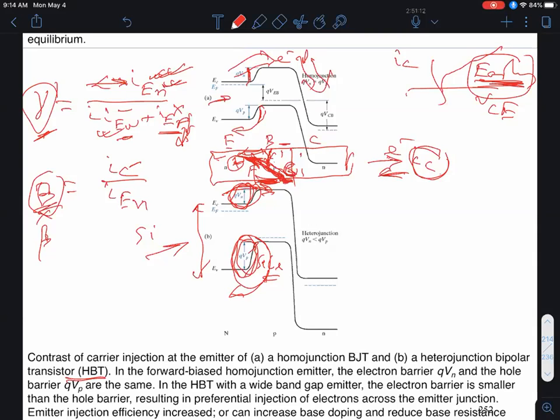And I'm willing to bet that in your cell phones, you probably have one of these silicon germanium, very, very high frequency HBT devices, which handles all the RF signals, communication with the tower, et cetera. In the past, these would be made up of much more expensive compound semiconductor devices such as gallium arsenide, but now, because of progress in silicon germanium HBTs, that's a much cheaper option for doing so.